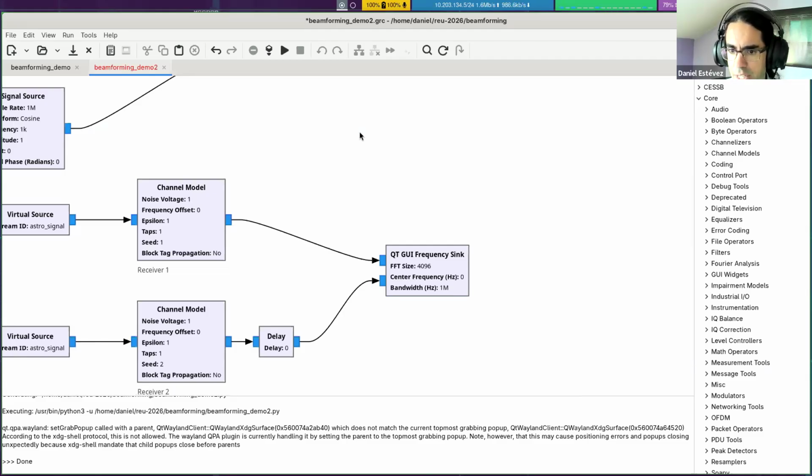And we want to collect as much signal power as we can, because that's what dictates the signal to noise ratio we get, and that's what determines whether we are able to detect the source at all or not, and also if we are doing measurements, how accurate these measurements will be. So basically, the better SNR we get on a source, the better.